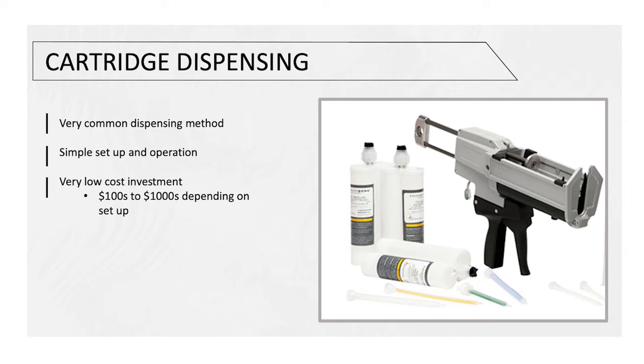Cartridge dispensing utilizes specialty side-by-side dual cartridge syringe barrels. These are Part A and Part B separated in a single cartridge that is dispensed through a helical mixing tube utilizing a cartridge dispensing gun. Because the A and B are separate, these are room temperature storable versus the single component pre-mixed and frozen syringes, which ship on dry ice and need negative 40°C specialty storage.